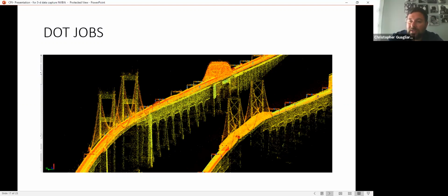And so we put 8 control points. We put 2 on either side coming across the eastbound. There were 2 when you got across onto the eastern shore. There were 2 on the other side going west, and then there were 2 coming across. So we painted those up, and we made sure when we went across that we scanned those, came all the way across the bridge, went back across and scanned those.